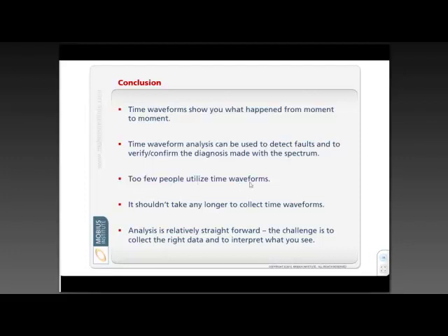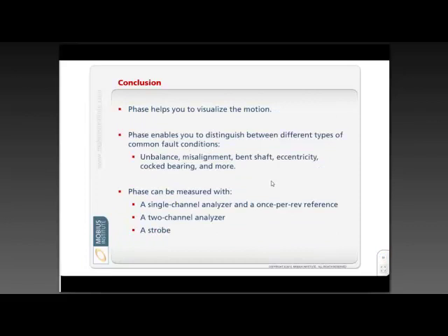Too few people utilize time waveforms. They're not used commonly enough. You really should be using them. It doesn't take you any more time to collect it, and it can take you all of 2 seconds to look and see if it's telling you something unique, and if it isn't, you'll be very fortunate. You'll be able to learn something you couldn't learn otherwise. So there's a lot we could talk about the analysis process, but not now.